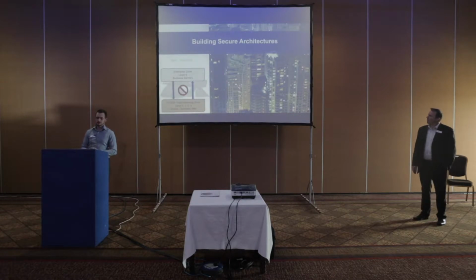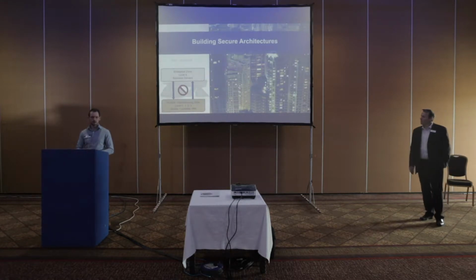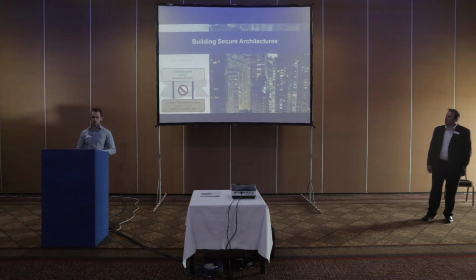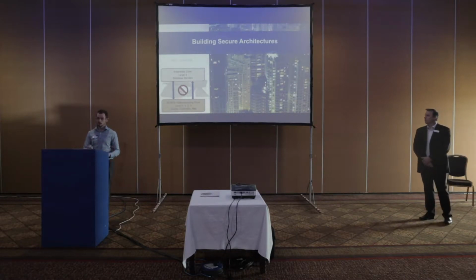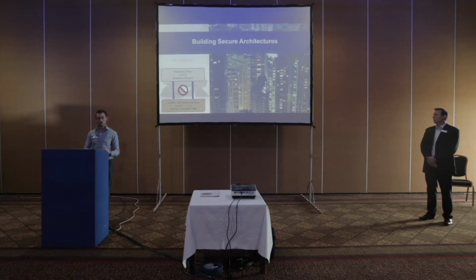So in terms of the past, we certainly presumed that by isolating our environments, we're inherently secure. By removing that connection to the enterprise layer, we have a secure SCADA environment at that bottom end. As we've started to progress, we know that we still need some data transfer between the two. We have to understand what our work orders are to be able to produce that product at the bottom end. So there has to be some way to get that data across. Yes, some of it might be manually written, but the chances are we're using things like USB sticks to get things between those two areas. And we all know what USB sticks can do to our environment.